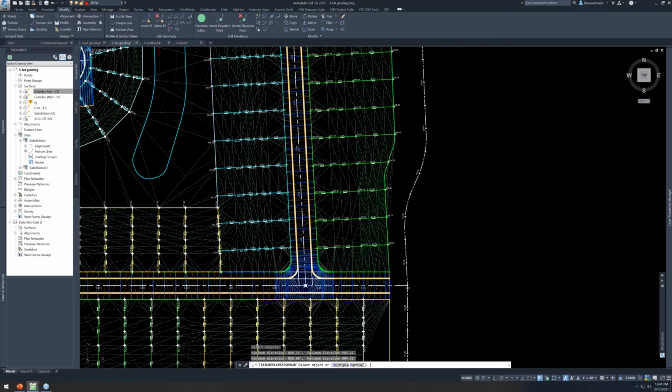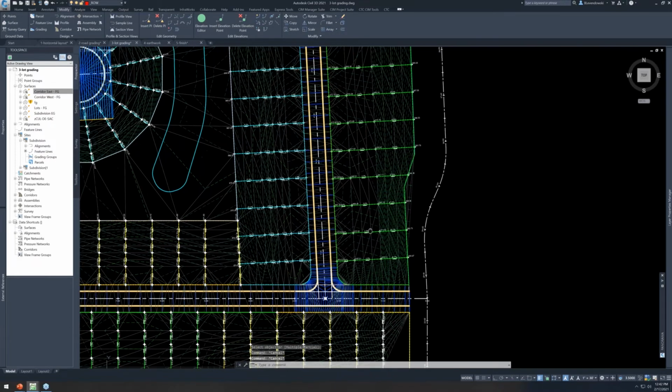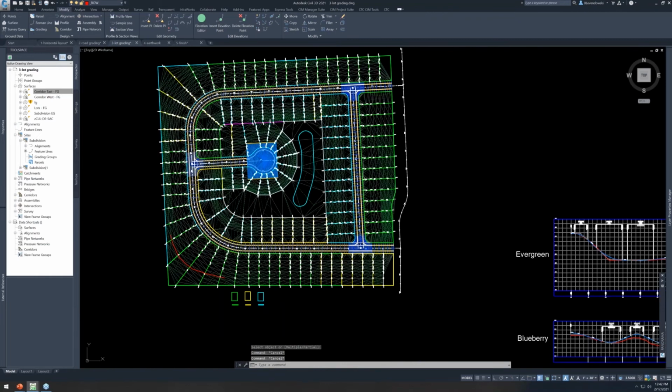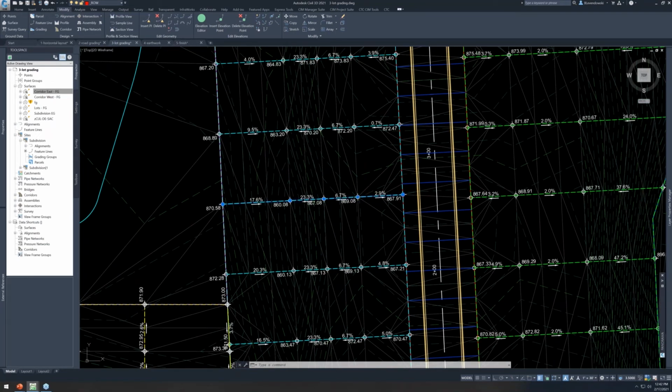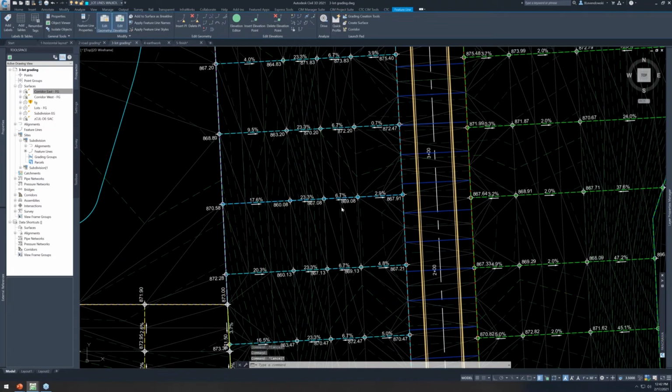Okay. Now that brought up the right-of-way lines, right? Might have seen some contour adjustments there. From here, all we need to do is adjust or refresh our grading families. I'm going to just do it on this side here. These are walkouts specified here.